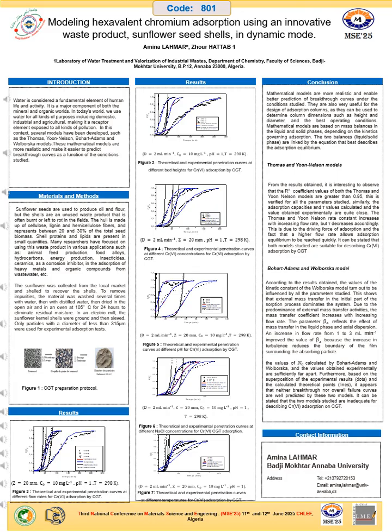Figure 6 represents theoretical and experimental breakthrough curves at different sodium chloride concentrations for hexavalent chromium adsorption by sunflower seed shells under conditions of bed height 20 mm, hexavalent chromium concentration equal to 10 ppm, temperature of 298 Kelvin and flow rate of 2 ml per minute. And Figure 7 represents theoretical and experimental breakthrough curves at different temperatures for hexavalent chromium adsorption by sunflower seed shells under conditions of bed height 20 mm, hexavalent chromium concentration equal to 10 ppm and flow rate of 2 ml per minute.